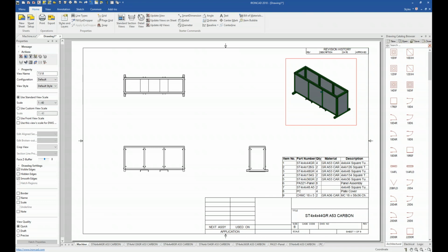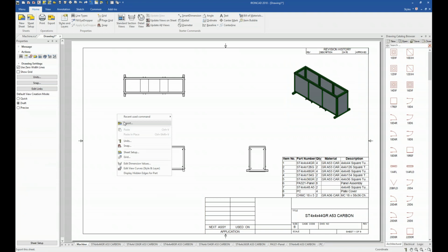So quickly, we can get our detailing process started right away with all of our sheets, and this works for any type of part: your assembly files, your main file, your individual part files, assembly drawing files. You can even use it for sheet level, and you can configure your views to have folded and unfolded views with the right information set for those different layers and properties, so your drawings are basically leapfrogged to the detailing stage. All you have to do is come in and final detail everything on your drawings, and then when you're done, save your drawings for manufacturing or export them to DWG-DXF for manufacturing.